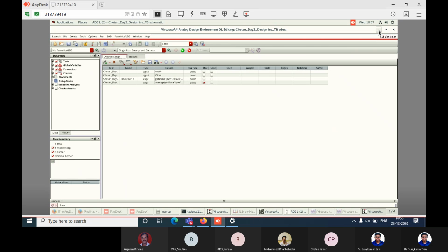In the first, let us take transistors with a fast speed of operation, meaning they are operating with a very fast response time. In the fast slow, your PMOS is fast and NMOS is slow. In the slow fast, your PMOS is slow and NMOS is fast, and in the slow, both transistors are slow. So these are the four different corners that will test the circuit: how the output power is behaving and changing at four different corners.